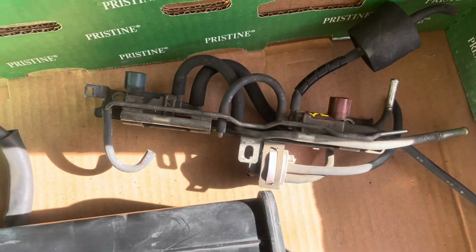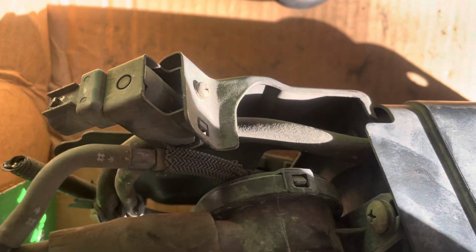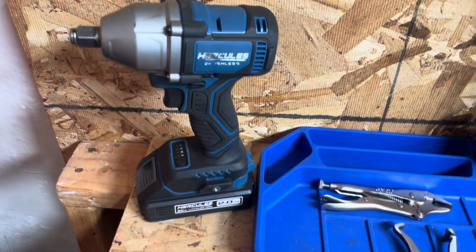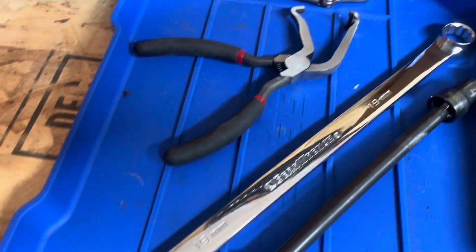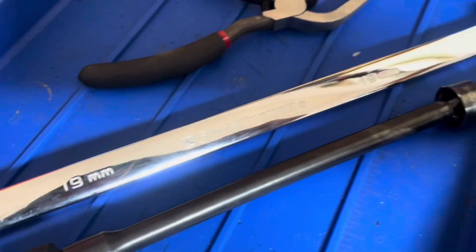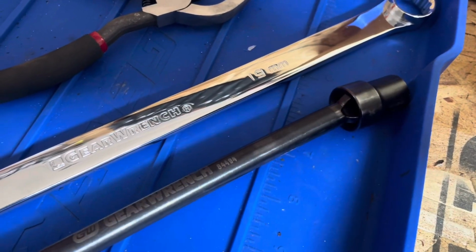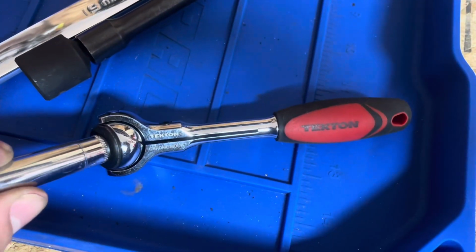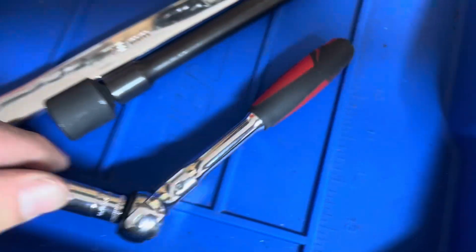I ended up taking quite a bit of tools to the junkyard, but only using a few. So I figured I'd lay out the tools I used to extract these various parts from the junkyard. The charcoal canister's under the car, so: Hercules 1/2-inch compact impact gun with a small 2-amp-hour battery, vice grips to hold the hood, connector disconnectors, 19mm gear wrench, long box end wrench to remove some stabilizer bars to give more access to the charcoal canister, which was held in by 2 14mm bolts. I used this gear wrench wobbly extension and this Tekton roto head 10mm.